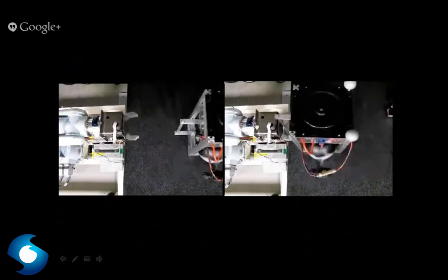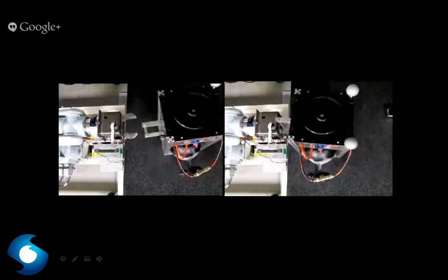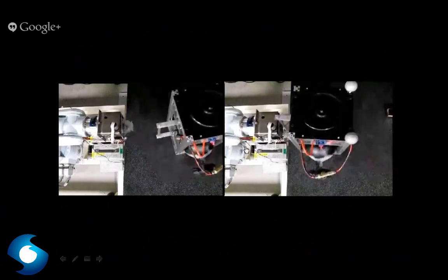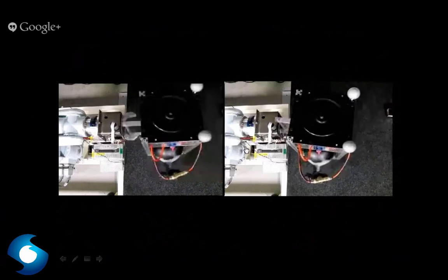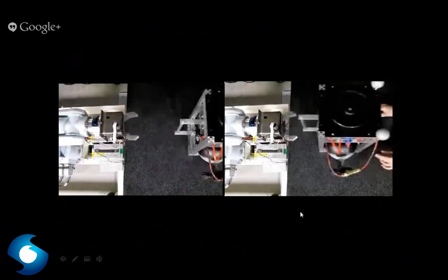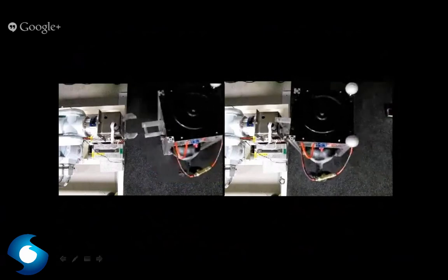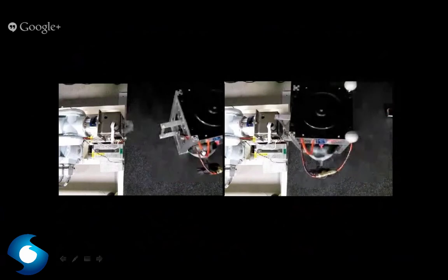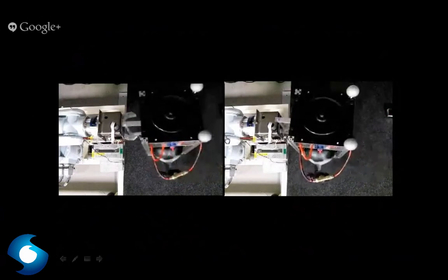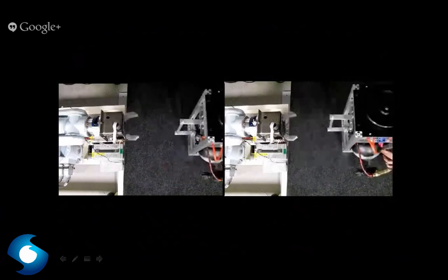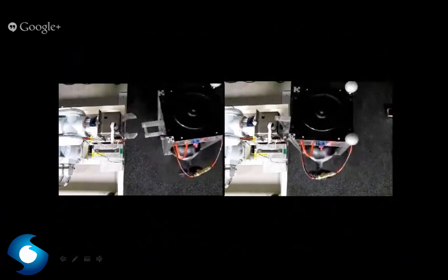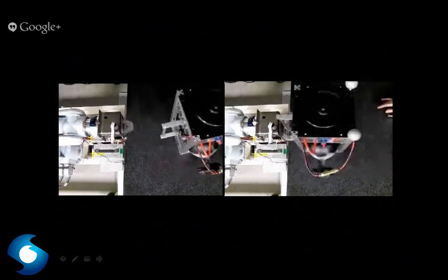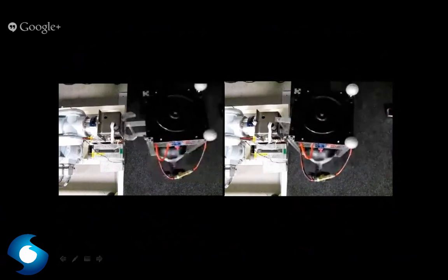So based on the measurement of the force, we conducted a kind of impedance control, or we could say a damping control. So the impact energy is, in this second case, completely absorbed in the manipulator motion. So if we can have this kind of impedance control or damping control for the manipulator part, we can increase the safety of this type of capturing maneuver.